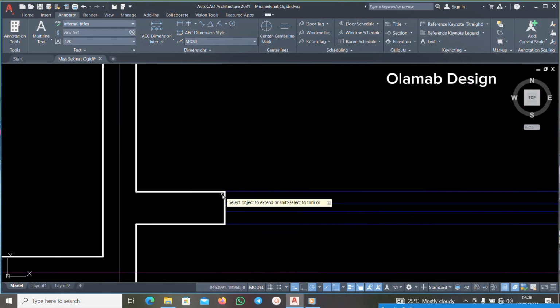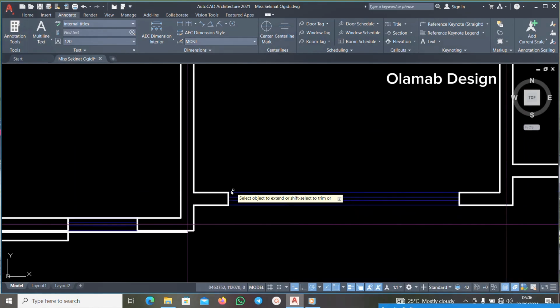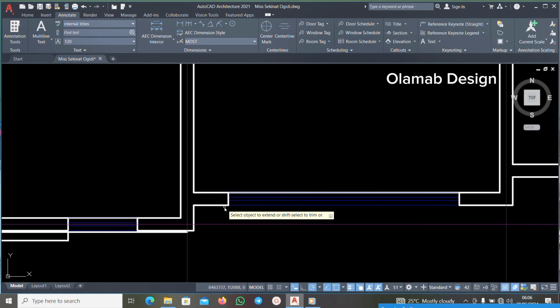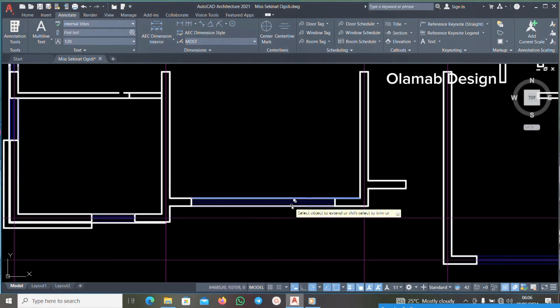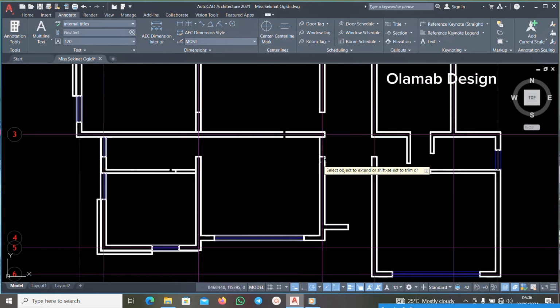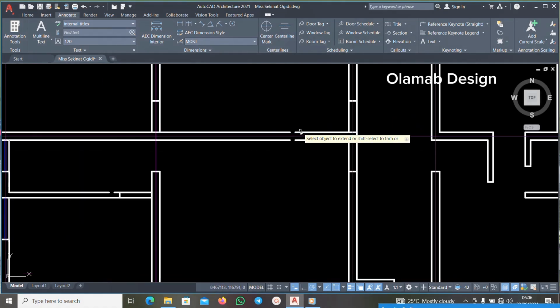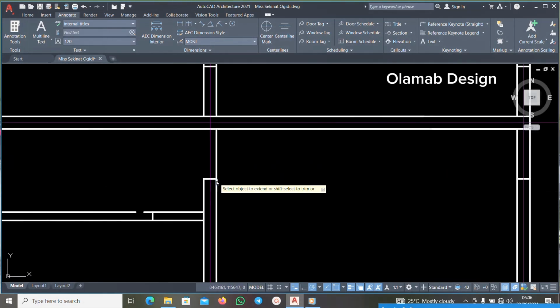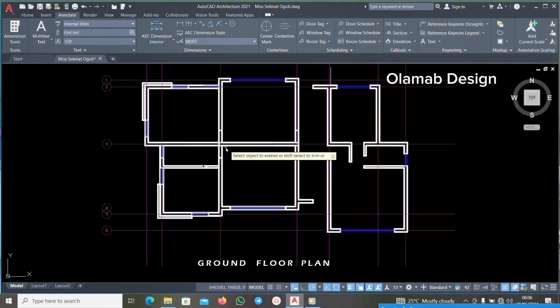Make sure you don't make mistakes on your general arrangement. This is an opening. As you can see how large it is, it's an opening. I will only be extending the wall, and the opening will still be there until I place all my columns. Make sure you don't place a column where there is an opening or an entrance. But if you feel it is very important to have your structural element there, then you need to contact your architect, to see if he can adjust any column, or rather any window, for you. Then you work hand in hand together with the architect.